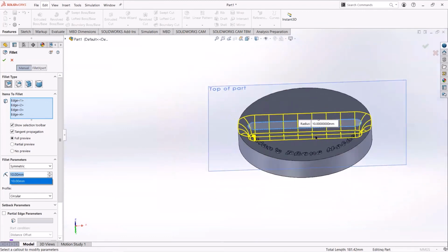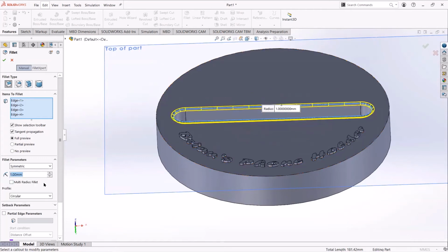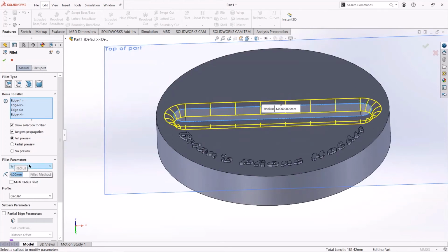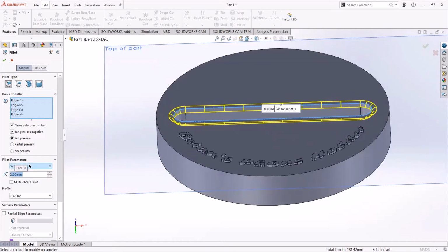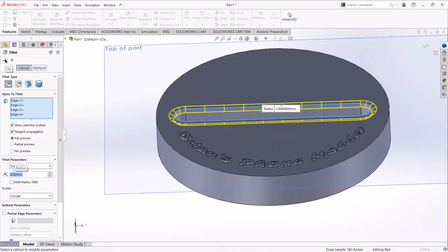So that's just some explanation. At first it was very confusing for me, but maybe not so much for you. What we're going to do is reduce the radius so that it's very close to the edge. So you'll get a feel for it simply by clicking 1 and then enter. Or you click 2 in this fillet parameter box and hit enter. And maybe you could do 4 and hit enter, and then you can get a feel for how much fillet. I like maybe 2 or even 3. 3 might make it look kind of nice, but then it might not give you the same rigidity. So yeah, I think 2 is better.